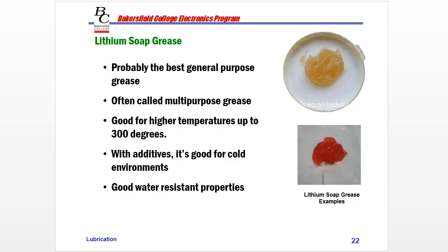The track is constantly moving up and down because the snow path, just like a road, isn't totally 100% smooth. So we're having some slight movement in some of the chassis joints. And so those have to be lubricated because we want to prevent that metal on metal contact, because over time we'll just wear right through the metal. So the grease is pushed in there and it is keeping it from having that metal contact.